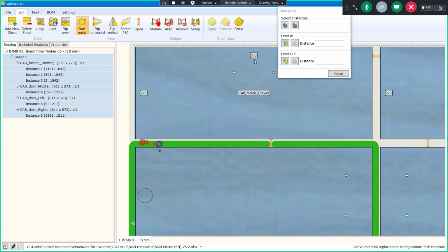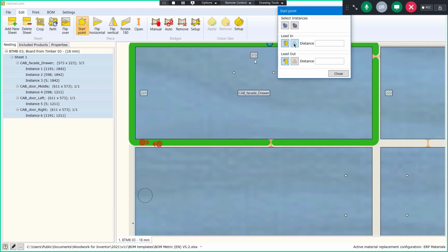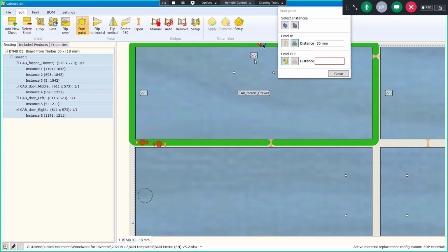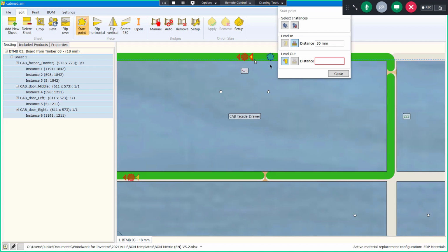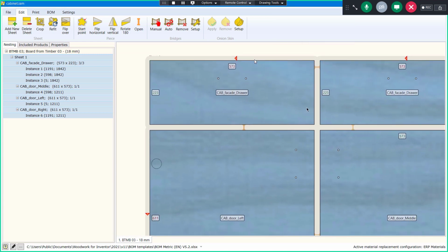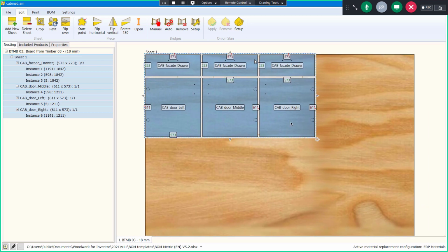Okay, and of course, when you're happy with the results, you can choose the lead in option, direct or ramp, or lead out options. Okay, when you have chosen one, you decide what is the distance of the approach and lead out. When there is nothing selected, you will see just a red window which indicates that something needs to be entered. Okay.